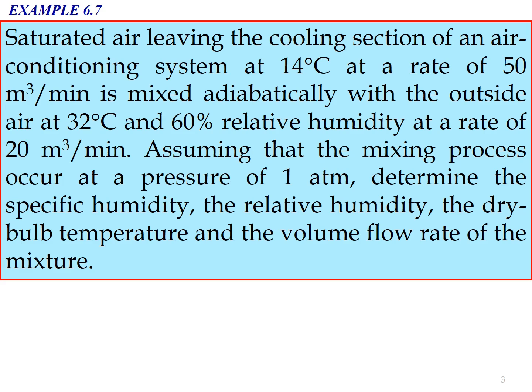Example 6.7: saturated air leaving the cooling section of an air conditioning system at 14 degrees Celsius at a rate of 50 meter cubed per minute is mixed adiabatically with the outside air at 32 degrees Celsius and 60% relative humidity at a rate of 20 meter cubed per minute. Assuming that the mixing process occurs at a pressure of 1 atm, determine the specific humidity, the relative humidity, the